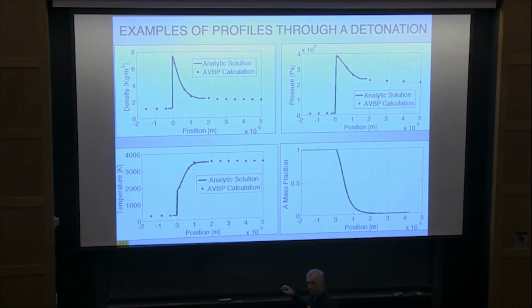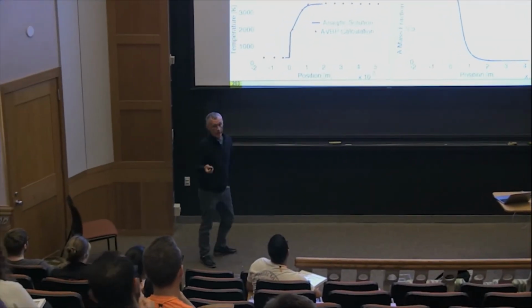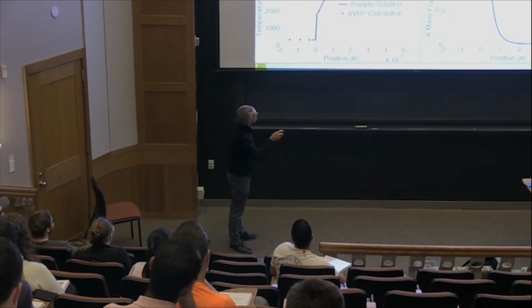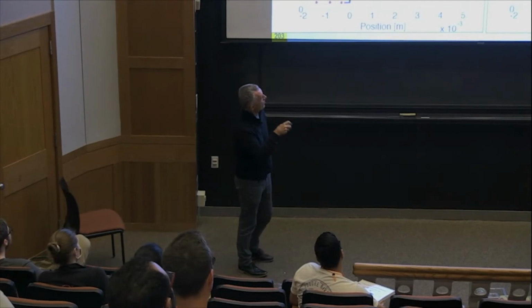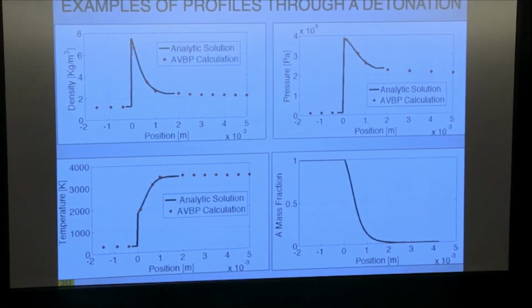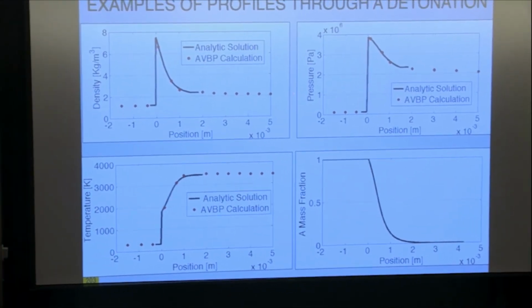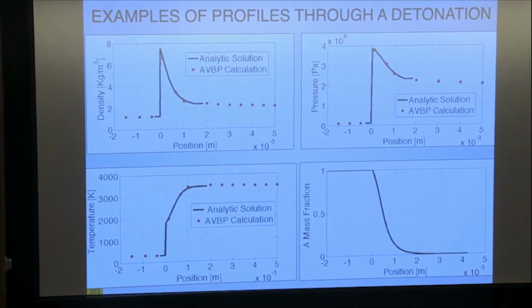There is no combustion, so you just take the expressions I've shown you, and you reach this point. Now you put this point into Cantera as initial conditions, and Cantera will compute combustion. You compute this part here. And so this is how you can, for example, compute this solution. You don't need a sophisticated tool. You can just use one zero-dimensional Cantera solution and the initialization after a shock, and you get this solution.